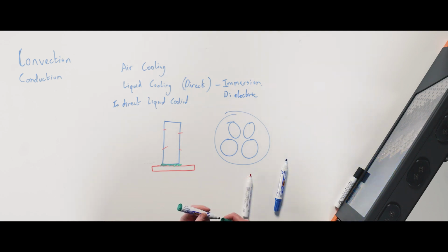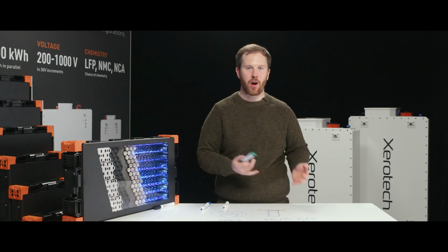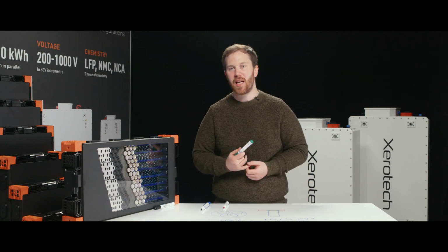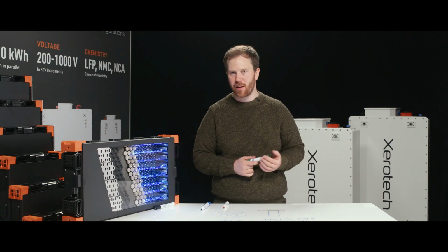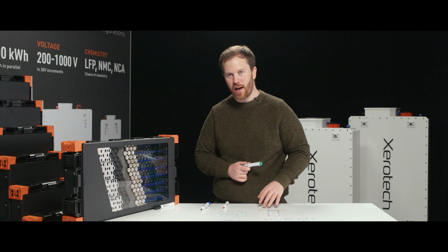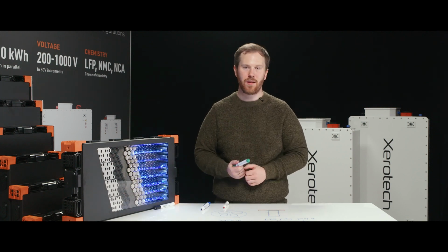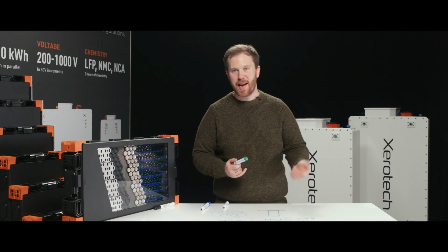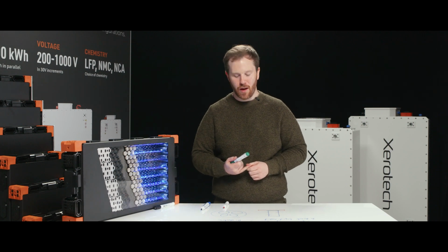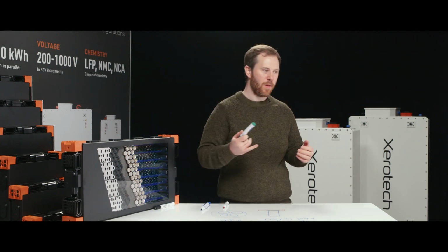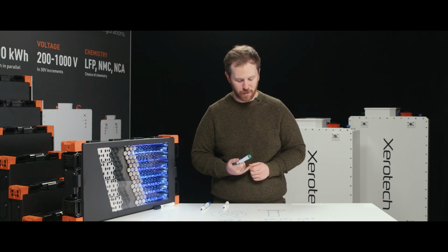Now, unfortunately, the laws of physics work against us here: electrical conductivity and thermal conductivity are actually the same thing for the vast majority of materials. There are only a couple of very rare exceptions, like diamonds and others, where it doesn't rely on electrons moving; something else carries the heat. What this means in a practical sense is that metals are really good conductors of heat and of electricity, whereas insulators are very poor conductors of electricity and, unfortunately, very poor conductors of heat.